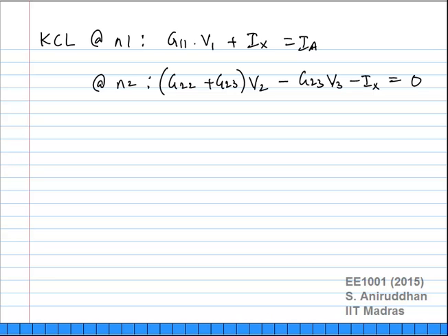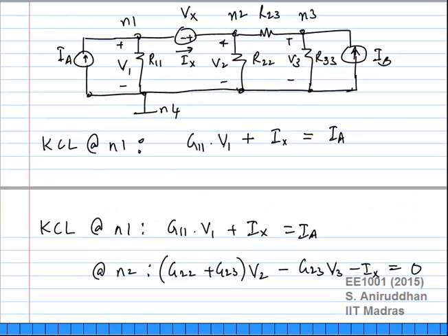What do you do next? What do you do about this equation? Now you can't write down the conductance matrix, and G times V equals I is not so straightforward anymore, right? In fact, you have an extra variable now, right? Ix. How do you propose we tackle this issue? Write V2 as V1 plus Vx. Any ideas how you would propose to solve this problem?